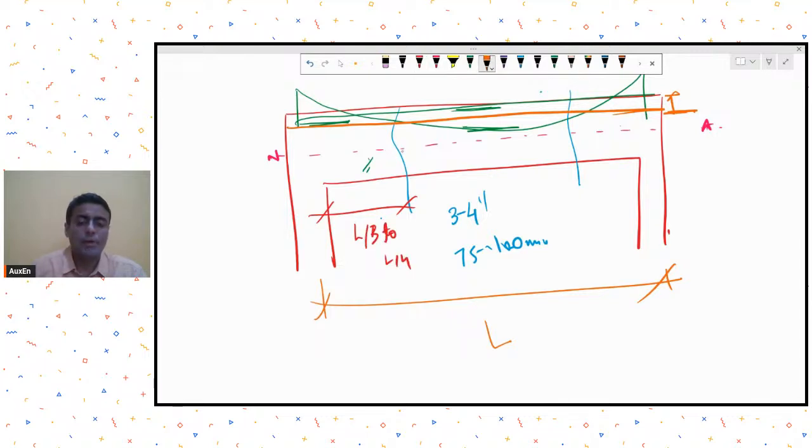And maybe over here I would like to cut somewhere near the neutral axis. Why near the neutral axis? Because below it I will be having my tension steel. Above the neutral axis my concrete is in compression. So slightly below the neutral axis, not on the neutral axis, of course I have to have a gap for cover also, maybe 25. So slightly below the neutral axis I can position my sleeve.